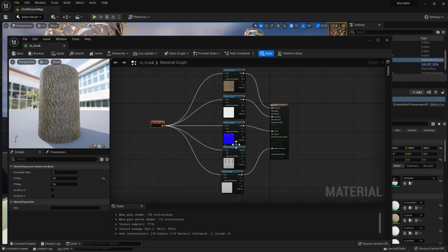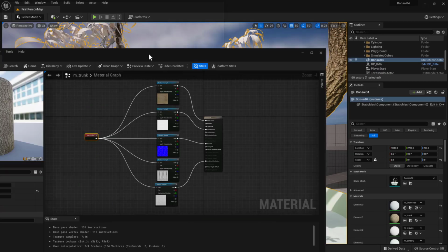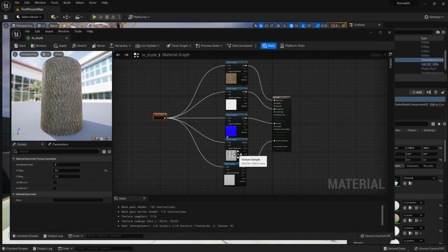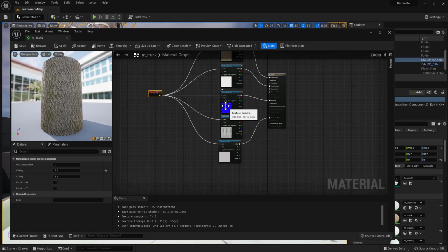This is if you just sort of want to use Unreal as like a little renderer and you don't want to get into all the technical stuff, you can set it up kind of like this. You can see in the texture swatches it's showing this tiling and stuff. It's working out well now. That's the way we want it. But if you zoom in here, you can see it's kind of tiling everything. That's fine because we have the texture coordinate set.